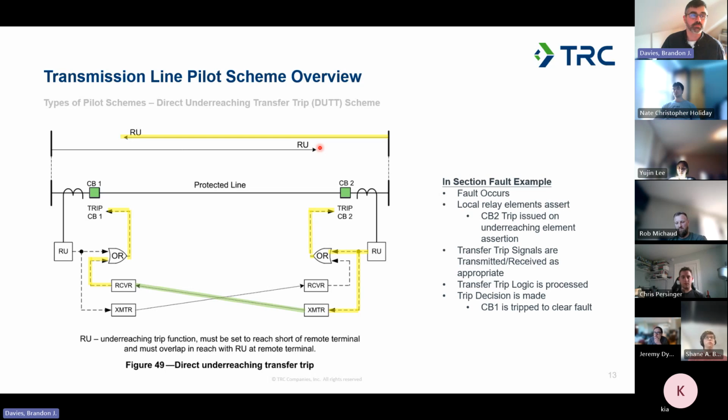as well, in a similar way that you may add a directional overcurrent element to the scheme. So it might actually be more than one overreaching or underreaching element. You'd typically be applying phase and ground protection for each of these elements as well. So that's really where Aspen comes in for these types of schemes: selecting and then validating the over and under reaching element settings and their reaches. Though you can actually model these schemes in Aspen.